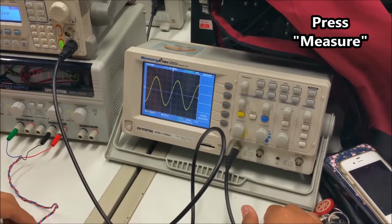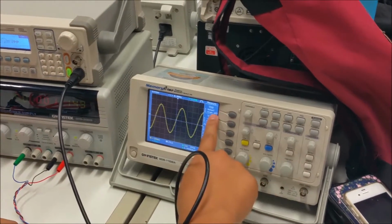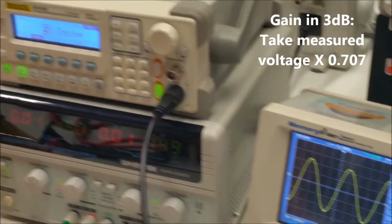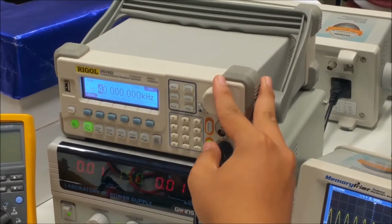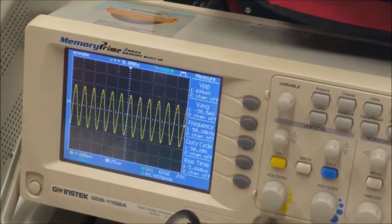Okay, now press on the measure button and take your measured voltage and multiply by 0.707 to get your voltage in 3 dB. Now increase your frequency until you have your measured voltage in 3 dB.